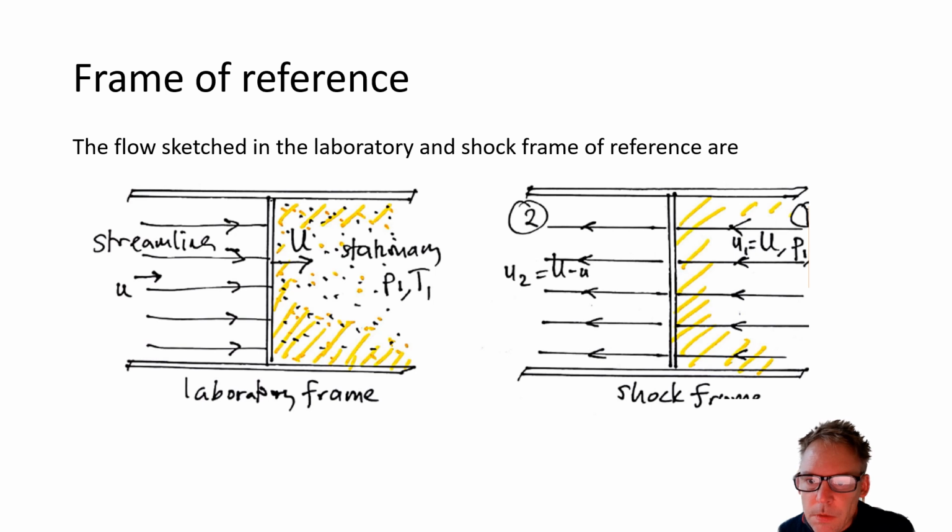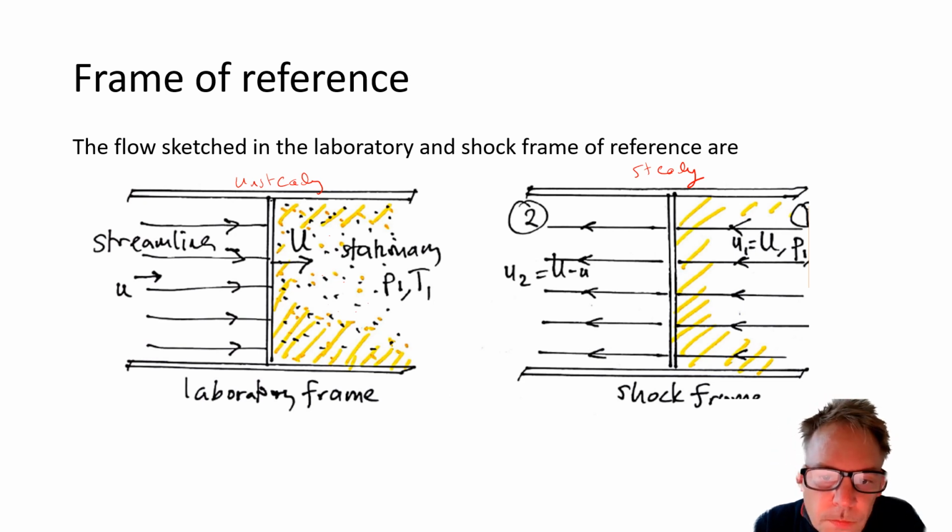This would be steady. This is unsteady. You can analyse both of these, but the steady case is a little bit more straightforward. So if we imagine this case of a shock propagating along a pipe, and this could be either through a valve closing, generating a compressive shock moving upstream, or a flame in a pipe, then what we have is a shock moving left to right, and upstream we have our stationary fluid because the flow signature hasn't arrived, it's supersonic and it's upstream. And let's assume that that shock is moving with speed u.